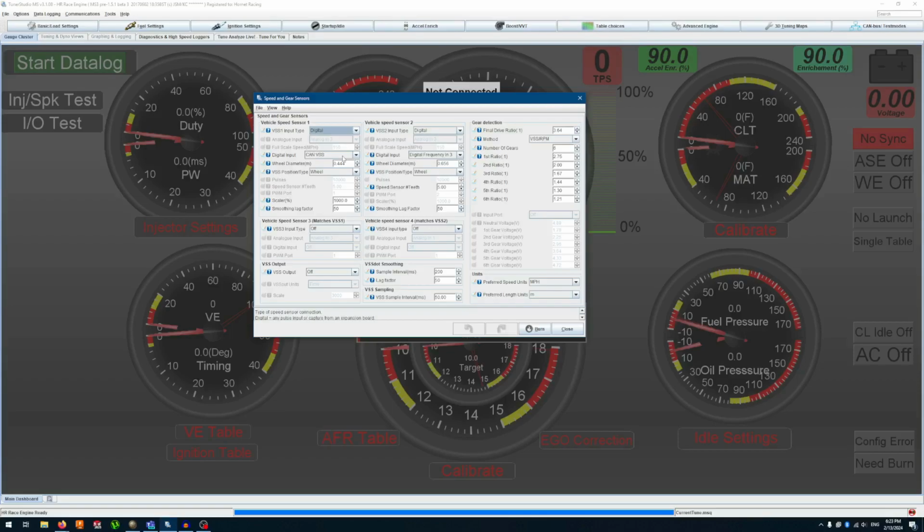So this is receiving the VSS, which is vehicle speed sensor. It's taking in VSS on the CAN line. You set wheel diameter, which is 444 millimeters, so 0.444 meters. VSS position type, wheel. Basically ours is on the axle, which is the wheel, but you could also have it on the drive line. That's what most normal cars actually have, in the transmission, and then you would set other stuff accordingly. Scalar percentage, lag factor, and smoothing factor. I guess this is just to make the data more consistent.